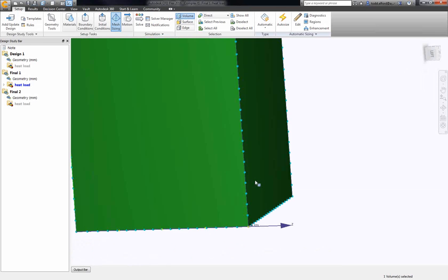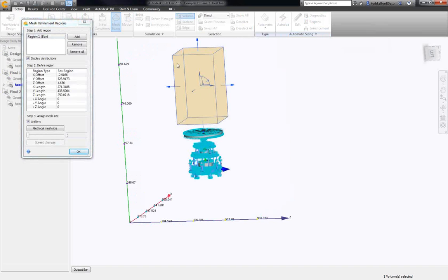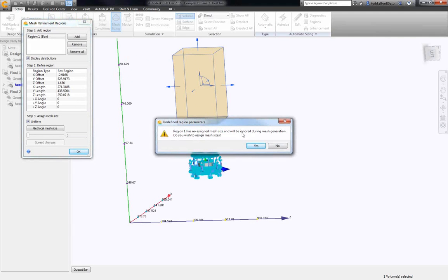Another quick tip if you're doing natural convection analyses: I put in a region above there, which isn't showing the mesh right now, but that's okay, just to make sure that I can capture that plume of velocity, because that's really what's driving the whole analysis. If I can't get that velocity profile right, I have no chance. Line mesh sizes, ignore. That's fine.